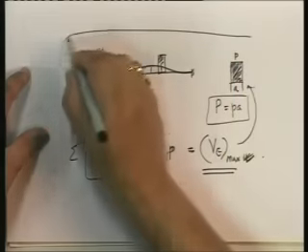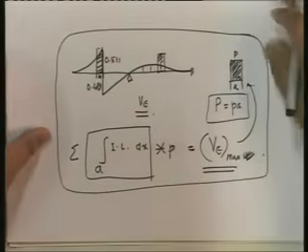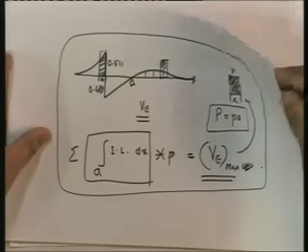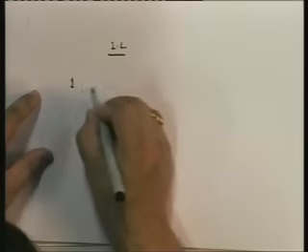influence. So once you place the load at the maximum influence, if it's a point load, the influence value multiplied by the load directly gives you the maximum value of the response under the moving load. And then if you are doing it for a distributed load like a tire load, then this is the procedure that you use. Okay. So in essence, the overall use of influence line is one, to